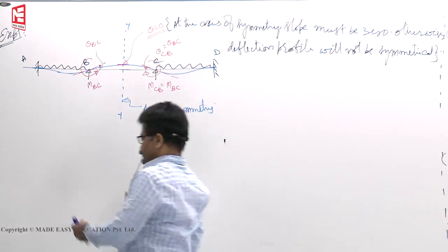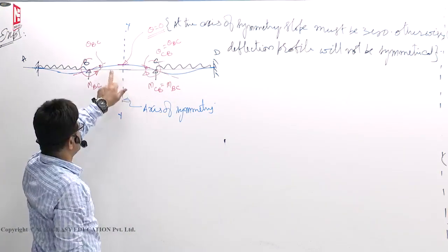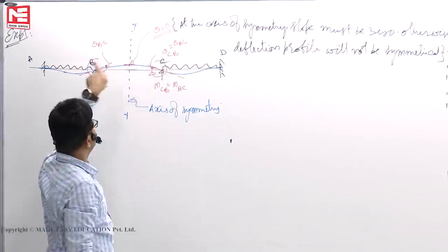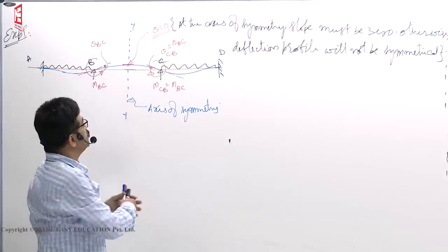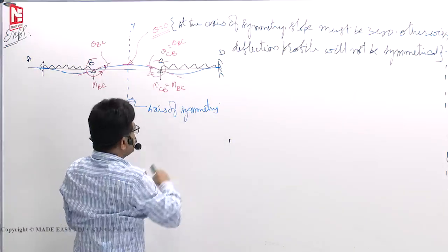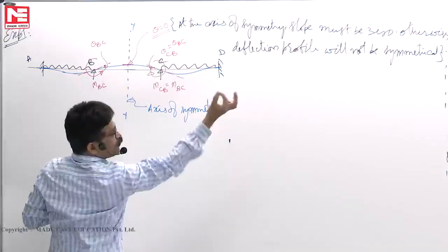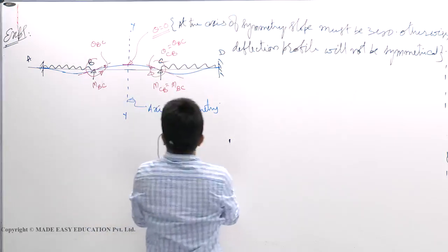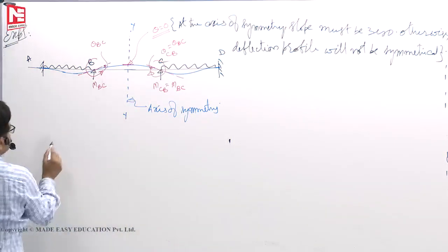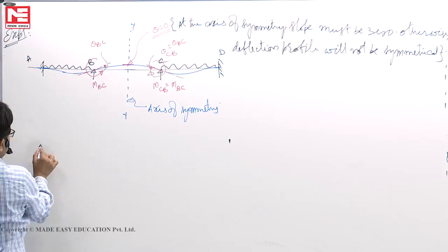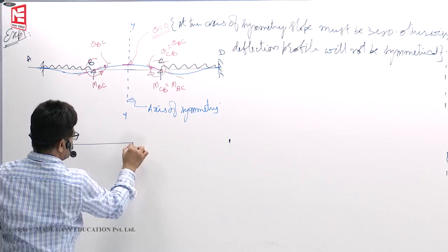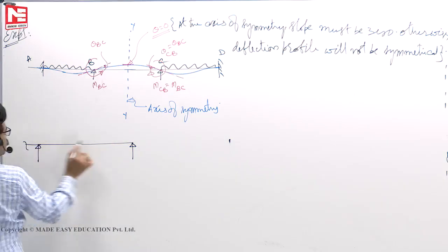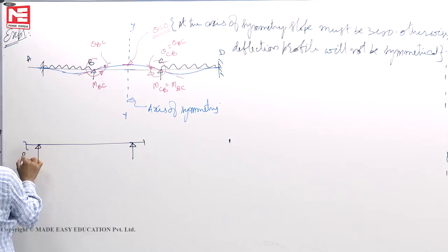Okay. Now, some deflection profile was there that we are taking. We don't want to deal with the applied loads, we want to deal with the end moments only. This is the case, let us say. Now we cut here and here. Take this profile alone, because there is no loading, only the end moments we want to take. So if I take the BC span alone, the free body diagram looks like this. This is the actual beam. Continuity was also there, of course, but we are taking only the BC span.